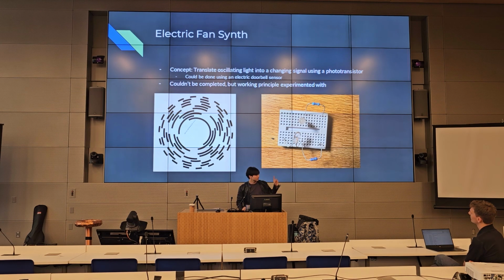And this thing here is supposed to be the thing that senses the spaces in between. There's a phototransistor, which is the thing below it, and an LED on top. Basically, every time there is a light that is allowed through, we have a high signal. Every time there's a light that's not going through, we have a low signal. And that's the operating principle.